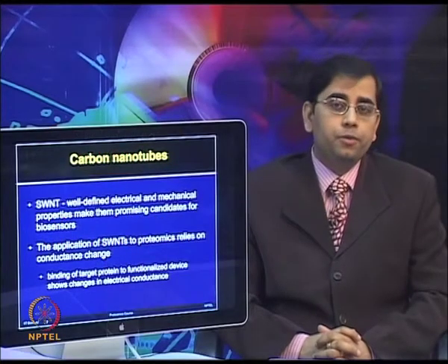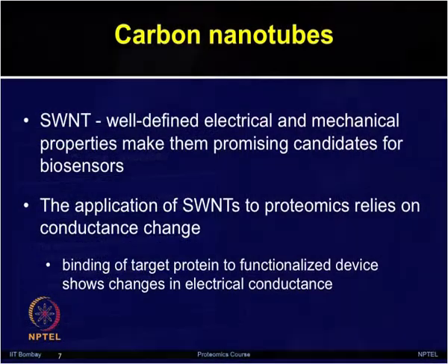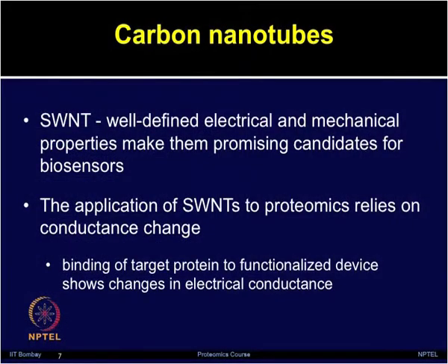The single walled nanotubes have well defined electrical and mechanical properties which make them very promising biosensor candidates. The application of single walled nanotubes to proteomics is based on measurement of change in conductance. When a target protein is functionalized on a single walled nanotube device, and a binding partner protein binds, the electrical conductance changes, and that is measured to monitor the binding.